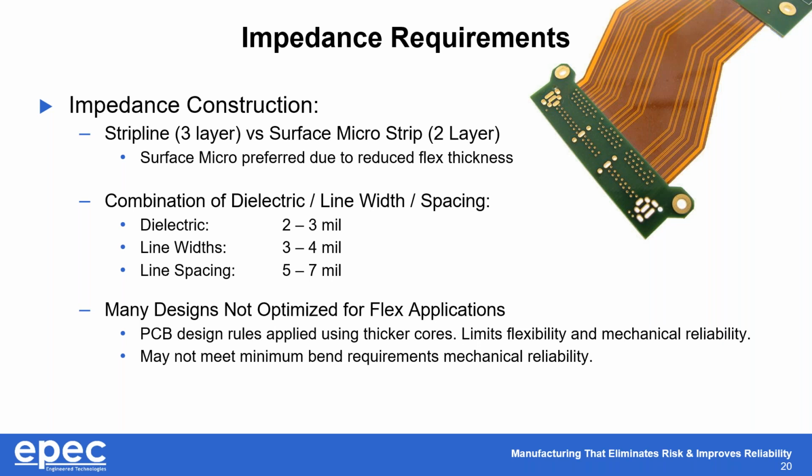And as I stated at the beginning of this section, many of the designs that we see are not initially optimized for flex applications. They're using PCB design rules, applying much thicker cores than what are ultimately necessary. Those in turn limit the flexibility and mechanical reliability of design. And we have seen many designs where they're just not going to meet the mechanical bend requirements that the customer has for that specific design.